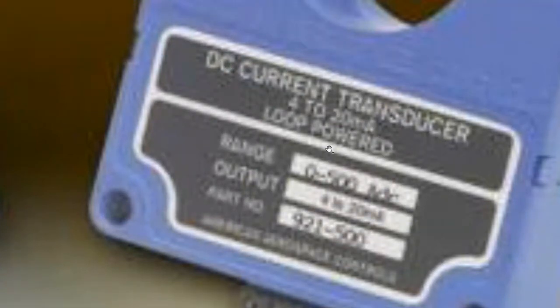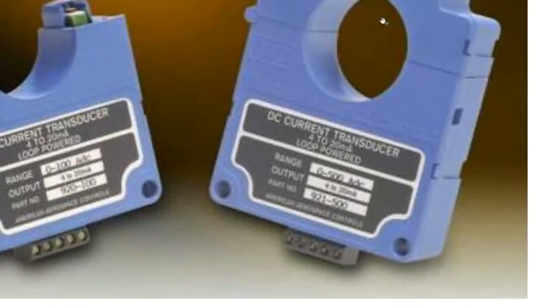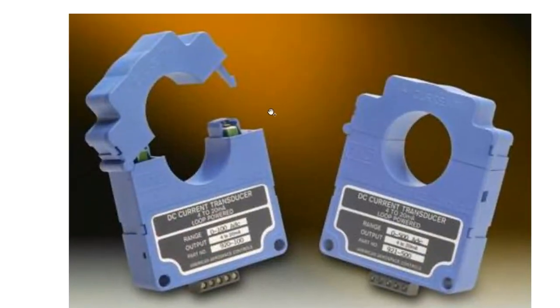Okay, and so what they do, can't quite read there, it looks about 500 amps. So these things are really designed to read very, very large current, like a big DC electrical motor or something. And so what you do is you just clip this over top of it, and you basically use Faraday's law that says if you have current running through a cable, it's going to generate a magnetic field. And so then what we're doing here is we're actually sensing the magnetic field.